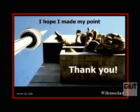Yes? Intrigued about the effects and the peaks associated with your upstream and downstream additional buildings. Yes. Second building. What I suppose flags some concern to me is that if we look at Brisbane, with a number of large high-rise mooted for the very near future, while we're all very excited about testing our tall buildings in wind tunnels, what we're not doing is actually checking what the effect is on downstream or upstream buildings, particularly when you could be talking of 4 to 5D, which in this case is potentially in the vicinity of 1.5 kilometres.